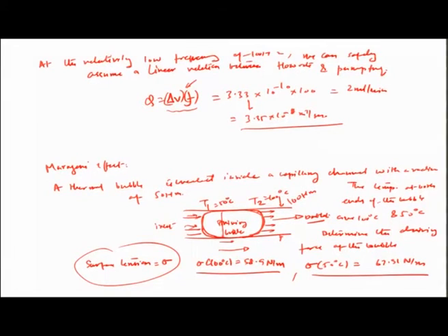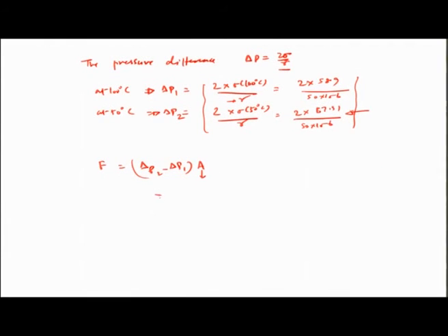And so we can approximately take this to be the cross sectional area, and this is pi r square, of course. So, pi times radius being 25 microns, 25 10 to the power of minus 6 square. So, when we compute this number here, we get 0.9 micronewton. So, this is about the force which will be needed to move a bubble through heating the bubble differentially on both ends, which is again a non-mechanical version of the actuation strategy that could be utilized for the purpose of this particular pump.